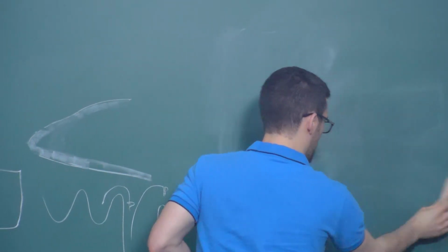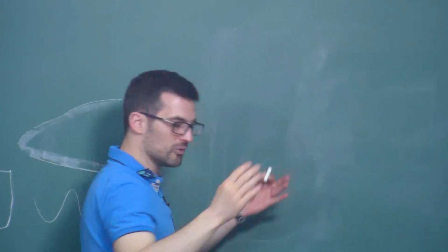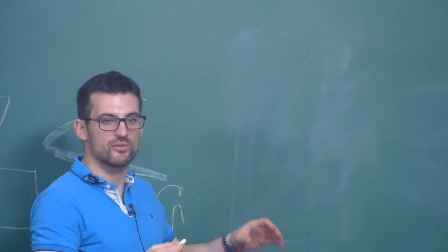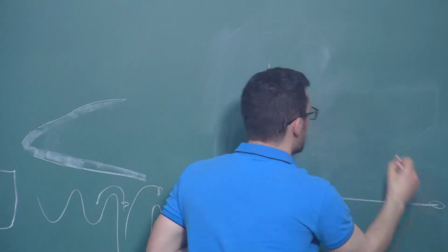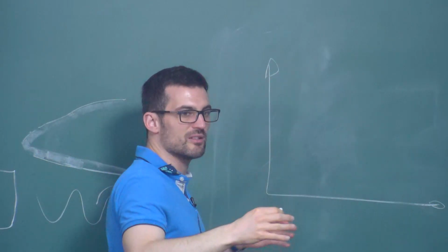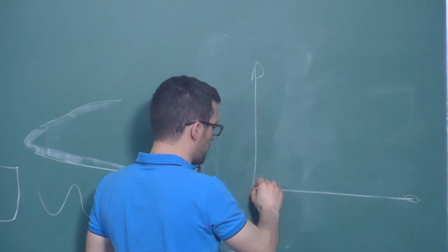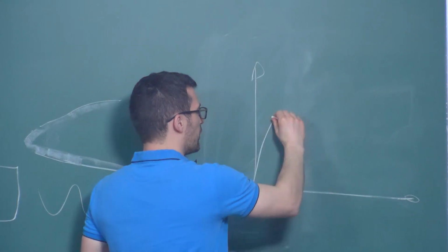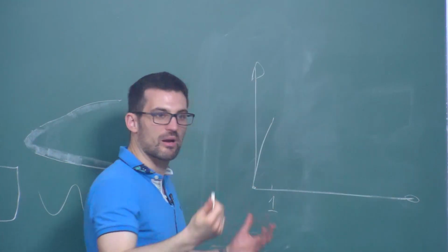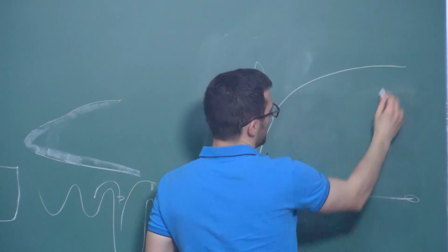let me plot it here. When you look at the data, some people look in the microscope, do interrupted tests, and so on. They can quantify. There's some literature on this where they quantify the number of cracks in the electrode particle versus number of cycles. And it is true that of course you start at 0, but then in the first cycle you go all the way here. It's a big jump. These are ceramic materials, so lots of cracks appear at the beginning. And then with cycles, it becomes something like this.